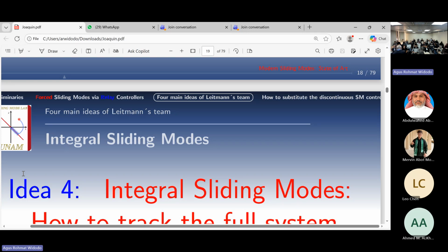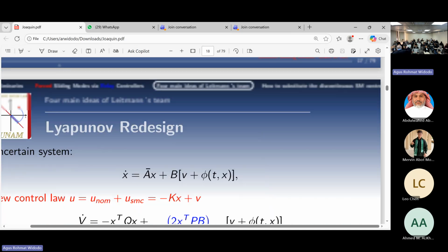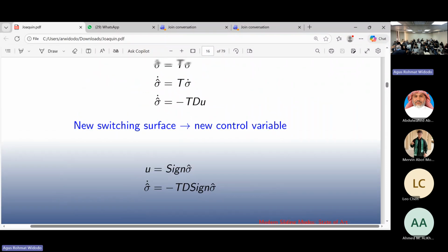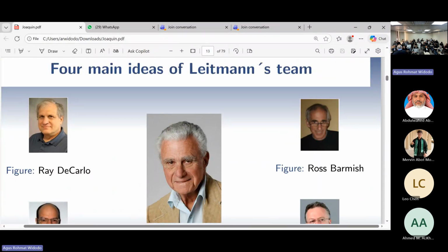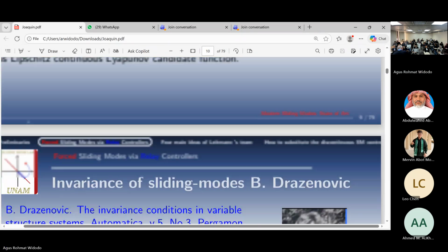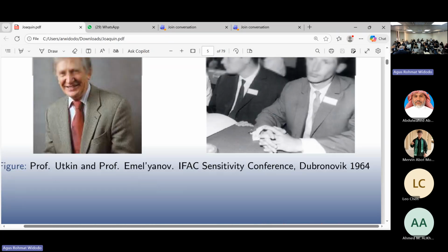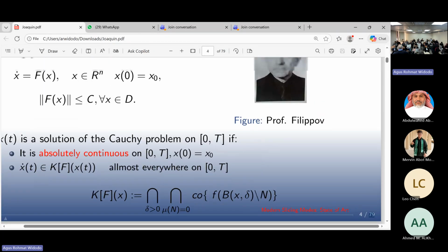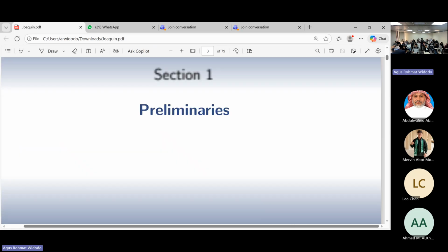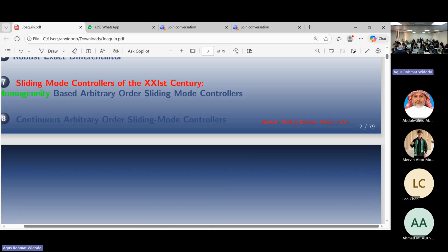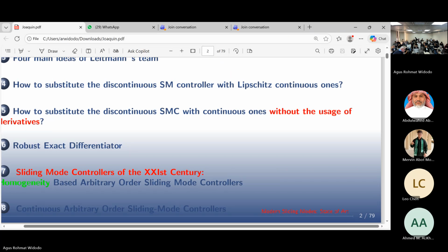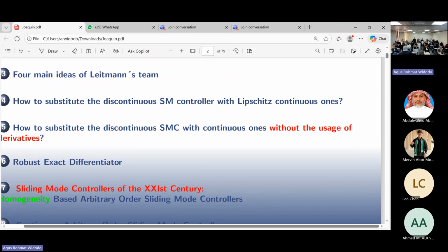Now you see this table. I'm perturbing it. Why doesn't it move? Because there is dry friction. What is dry friction? It is a sign function. You cannot see how it switches, but it is the same function. It's discontinuous. If you model the friction as linear, will you stop or not? For sure not, because you will have asymptotic convergence, isn't it? You will have minus kx, so the bigger the gain, the faster you go to zero, but you will never reach it. So your car will not stop. That's the point. Without real friction, your car is not stopping. So this means we really need the sign function. Without it, it does not work.